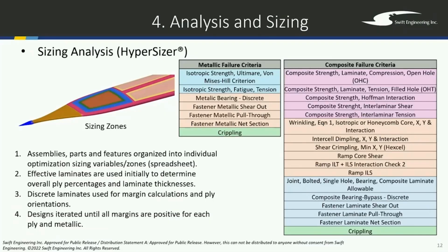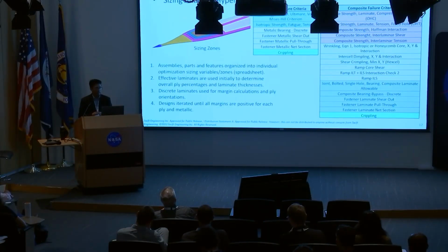It had about 5 bulkheads all the way through, and composite laminate, core composite. You can see the yellow borders. Those are the core ramps, and the salmon color are where the core is. Of course, you have the same thing on the underbelly, the under skin, as well.